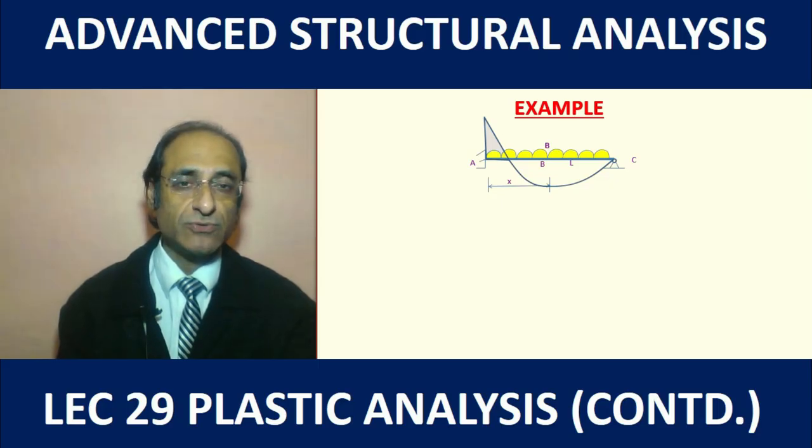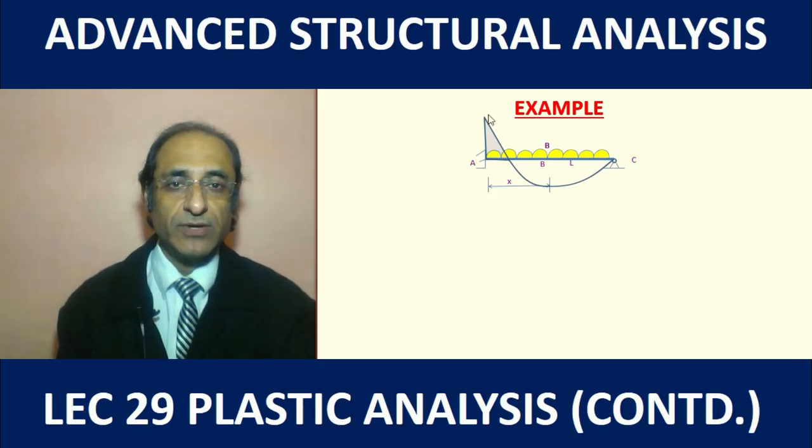We just need to know the qualitative shape of the bending moment diagram. For example, here we don't need to compute the values of the bending moment at the key locations as per the elastic analysis. In the longhand method, we need to determine these values from analysis, so this step is not required here.